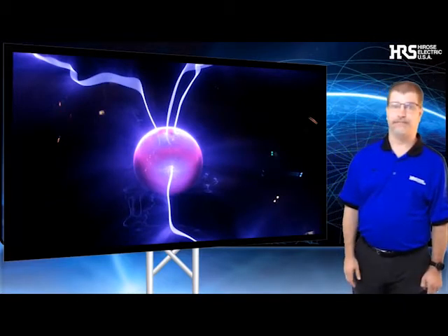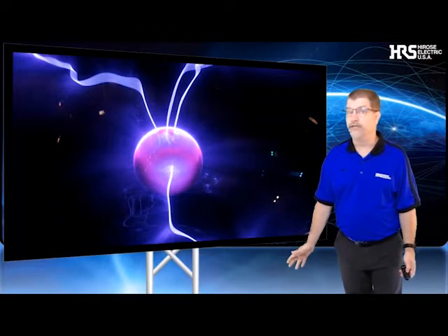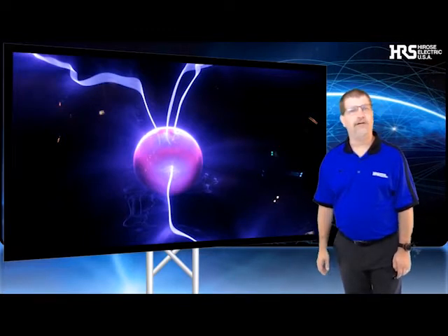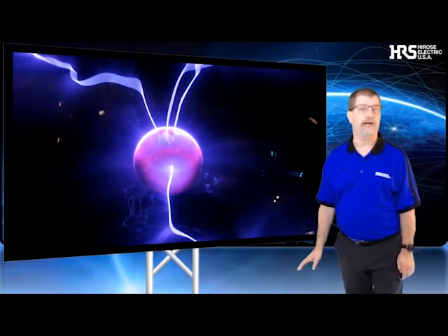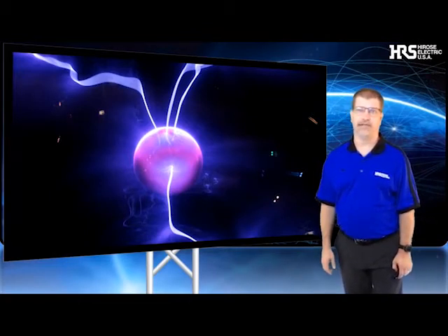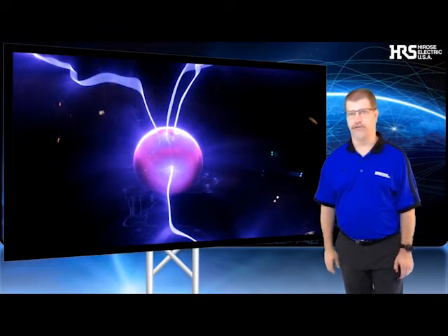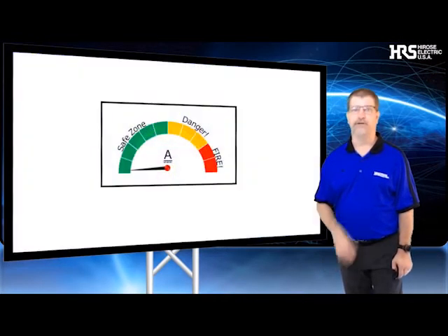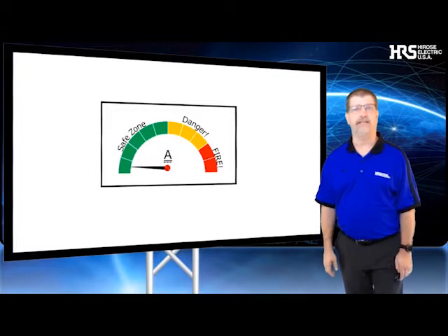Understanding the required current is the second half of this question. What is the peak amperage needed for the application? Are you running current over more than one contact, maybe multiple circuits? Are you dividing a higher current need across more than one contact, but it's only a single circuit? For power connectors, we need to understand that application and how that current will be distributed across the connector. If your current is running over a single contact, then this rating is simple and listed in the datasheets.